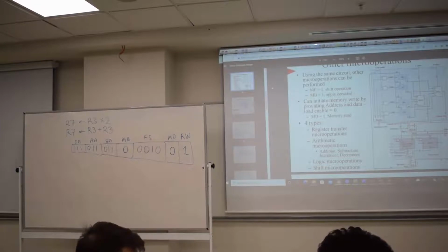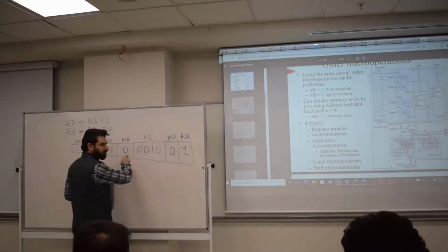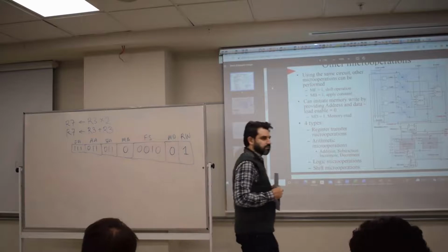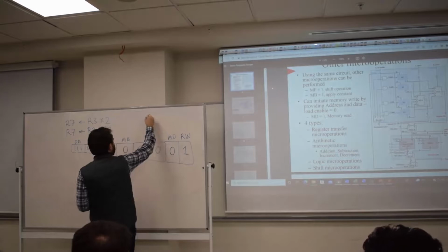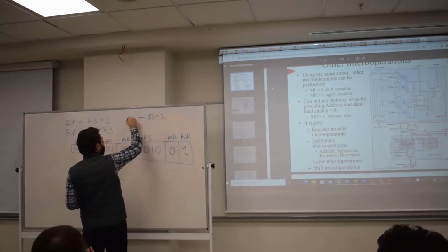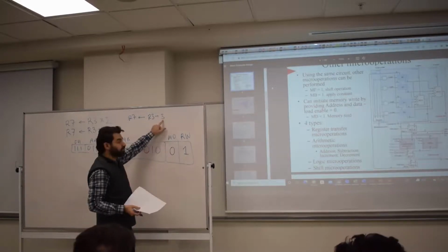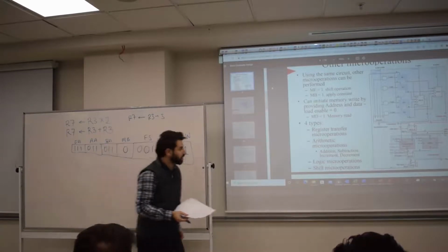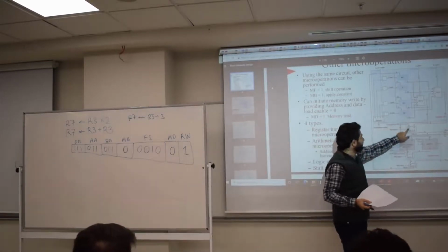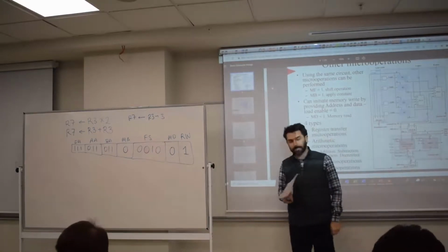You got a question? When would we use MB? MB? For constants, right? Yes, right? So anything like, I don't know, R3 plus... Yeah, R3 plus 3, for example. Then we would... R7. You can directly use a constant, because this is coming, as you will see, from the instruction. We will read that value from the instruction, and then put it on that bus here, constant, right here. So you can now select a 1 to put that into bus B. Okay? You have got a question?